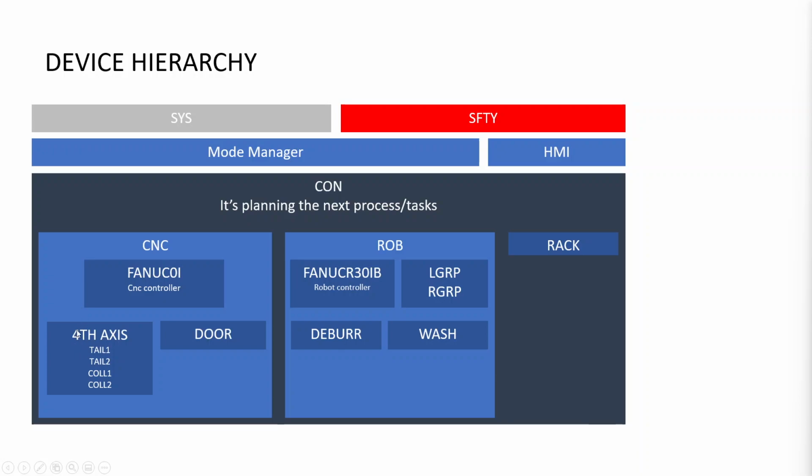I want it to behave and act in a very consistent manner relative to the conductor. The conductor and the CNC's communication back and forth with one another should be identical, whether the CNC uses a FANUC 0i controller, a Heidenhain, whatever. I want to keep the communication between the conductor and the CNC very consistent. That way, if you adapt this logic to another system, you really just have to drill into the specific low-level control of the controller itself.